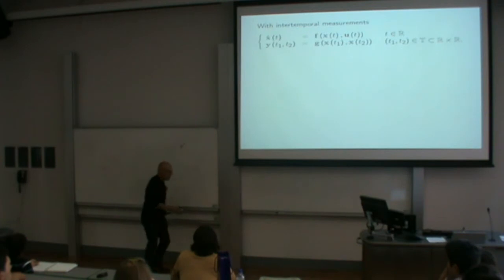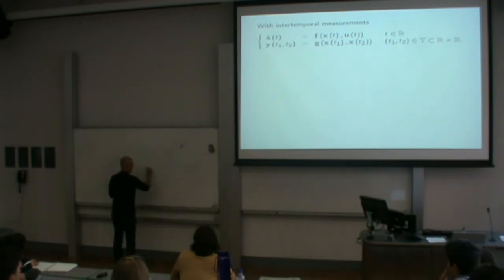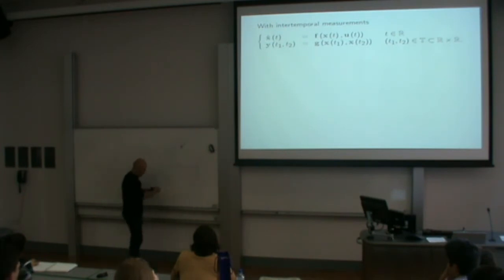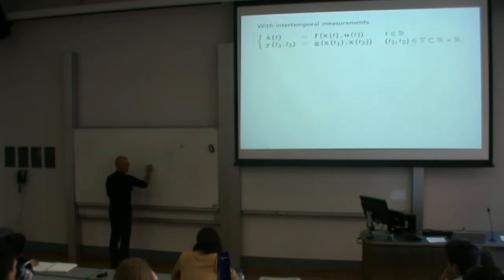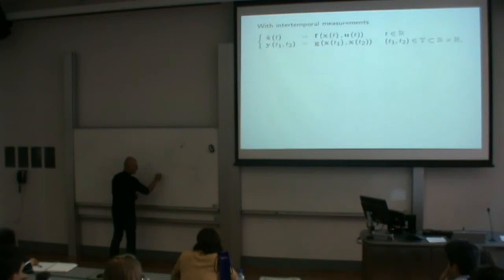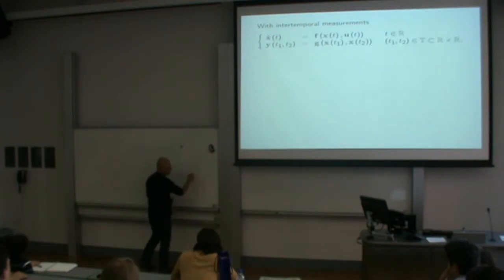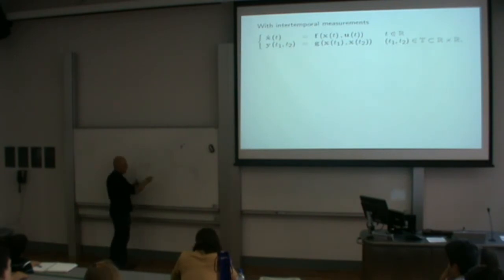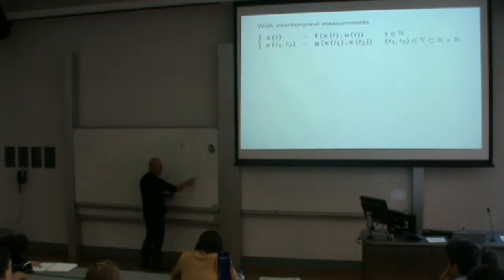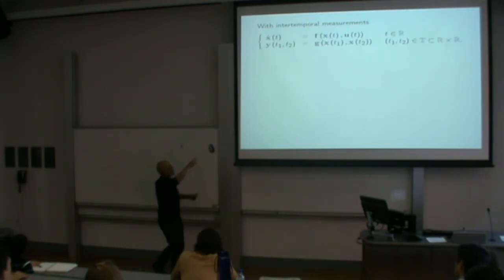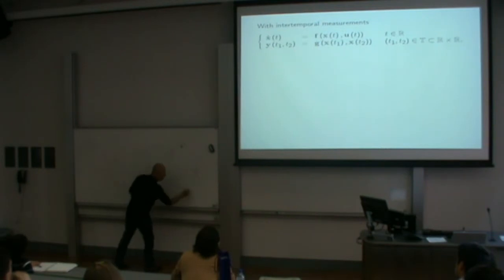Because in our problem, you have one robot here, and one other robot which is here under the water. This one, at time T1, sent a sound that propagates, and will be received at time T2. Of course, they communicate together, and with this message, he tells the other one, I am sending a ping sound at time T1. So this one knows that he received at time T2, and he knows this information about T1, but as we can understand, the measurement depends on both times, because both robots are moving. At time T2, this robot will be here.